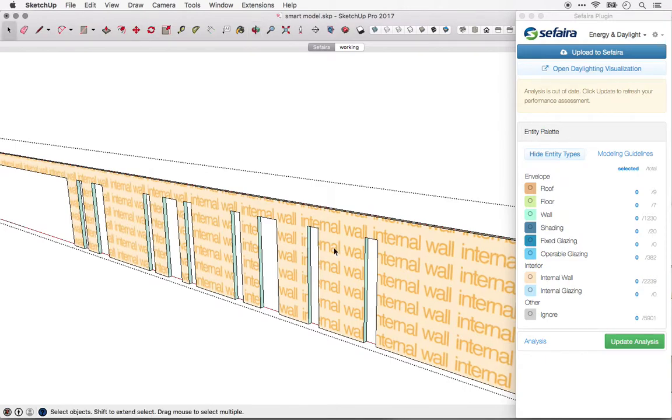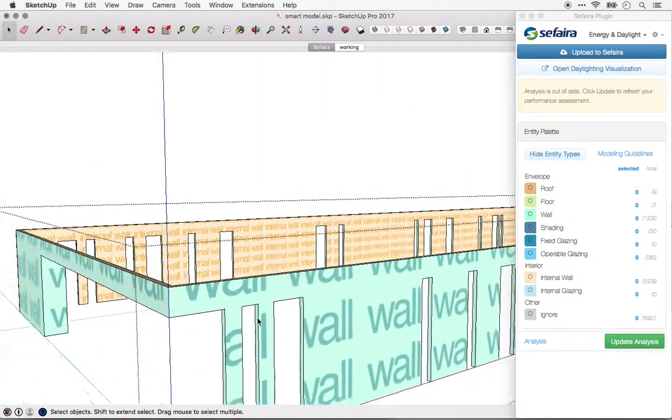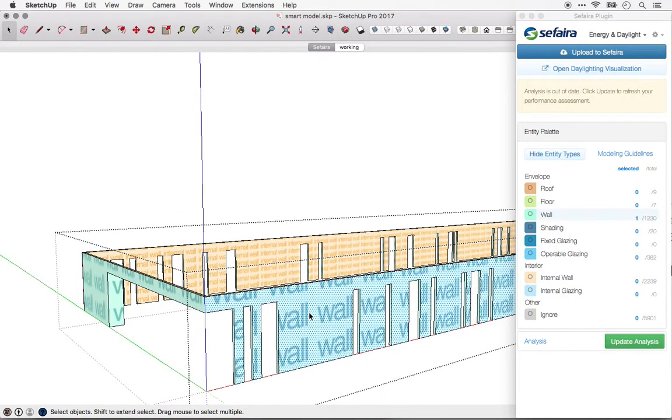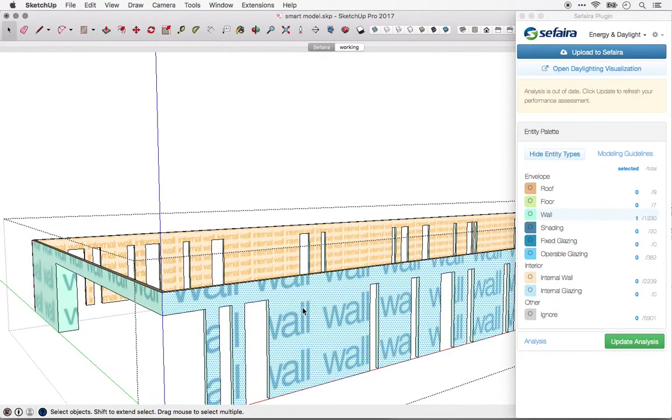The easiest thing to do is oftentimes to tag all of the wall geometry as interior, and then go around the building and simply tag the planes that should be exterior. And this is because there often ends up being more geometry that's interior than exterior, and that way you end up making fewer errors and not accidentally having exterior walls on the inside.